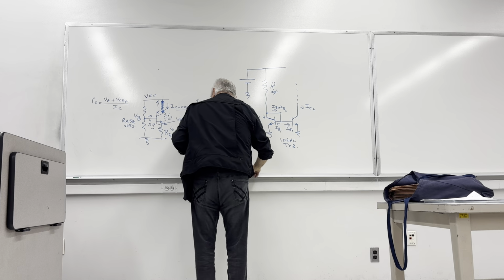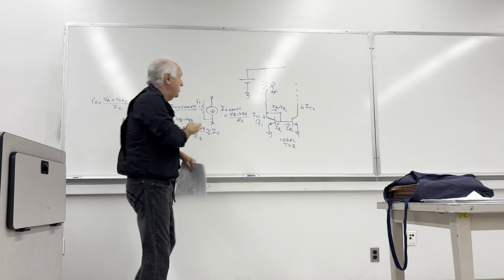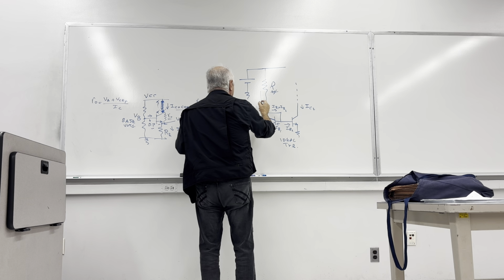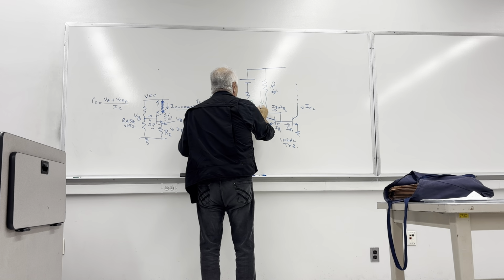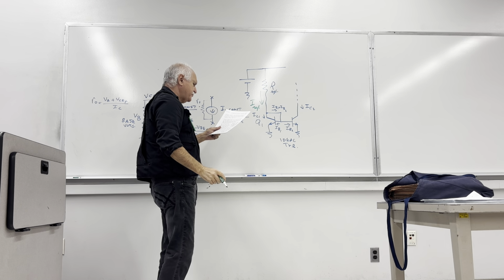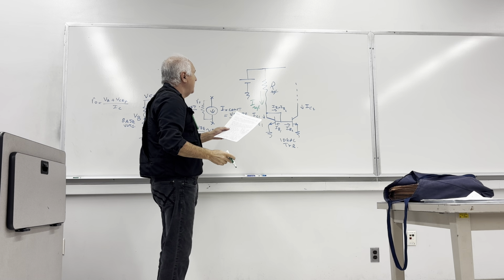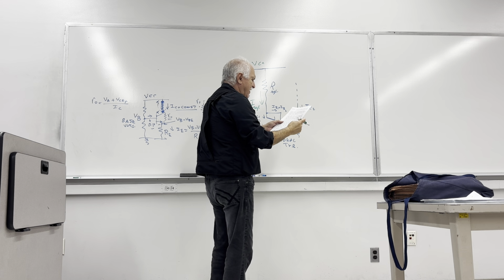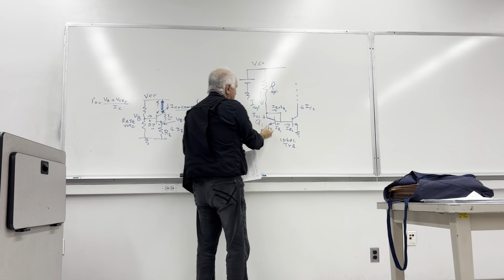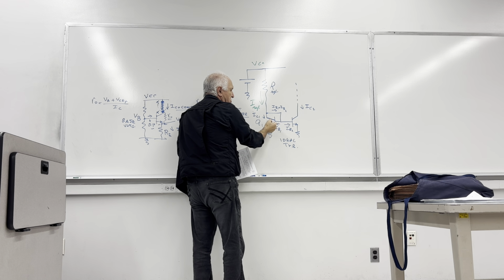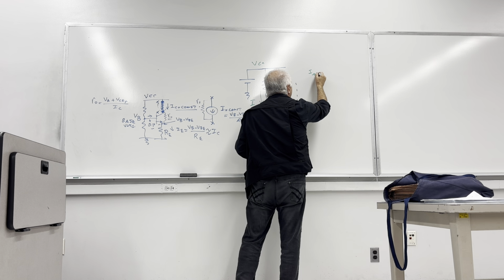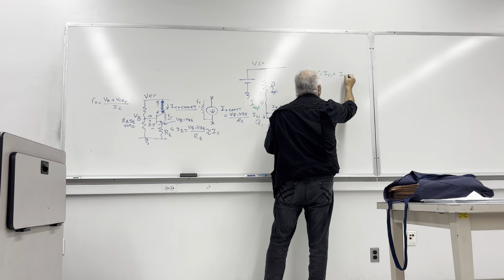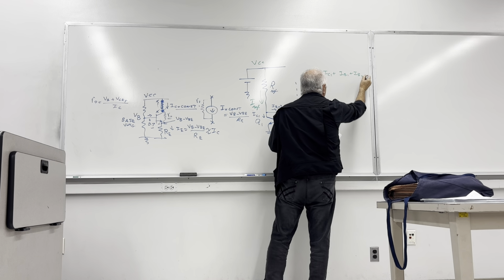And then if you establish a current in the reference resistor as Iref, I reference in that resistor, then with the help of the equation that is established there, we can validate: Iref is equal to IC1 plus IB1 plus IB2. That's equation number 1.